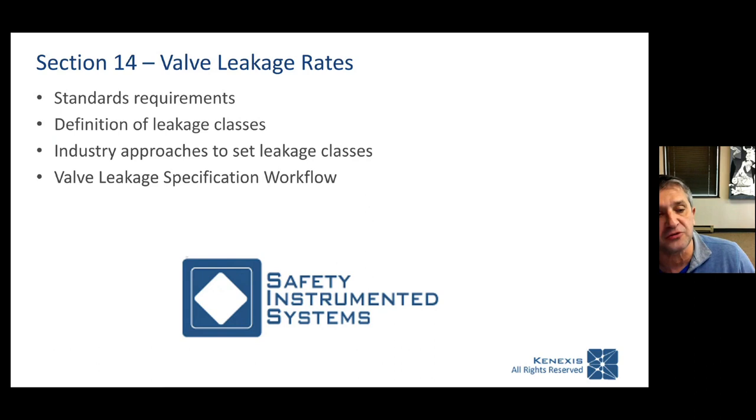What you really want to do is put in a double block and bleed or a double block and pressure system that is going to give you a more positive isolation between those two environments. And that double block and bleed, double block and pressure assembly is going to be tolerant to a pretty significant amount of leakage, because all that leakage is going to a safe location instead of passing from one atmosphere to the other.